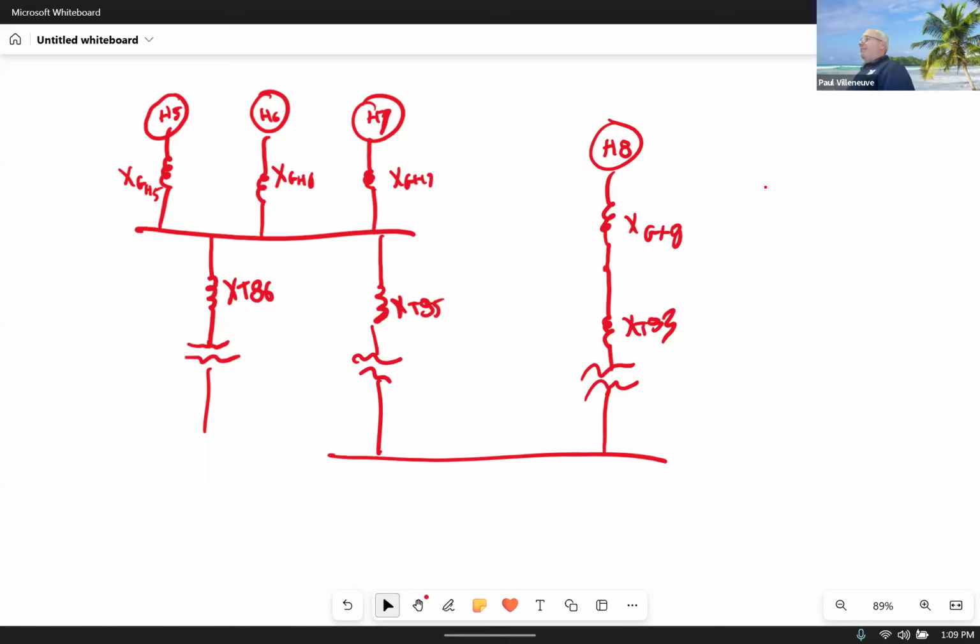But now everything is modular. It's like the size of this desk. You can actually put what's called GIS, gas insulated. That's the SF6. You can put it inside of a room like this, and it would be a 345 kV, and you can walk in and it's all grounded. It's perfectly safe. So when you're in fancy towns, where nobody wants to see overhead lines, they would do vacuum, or air if it's a low enough voltage, or SF6, just to keep it looking prettier.